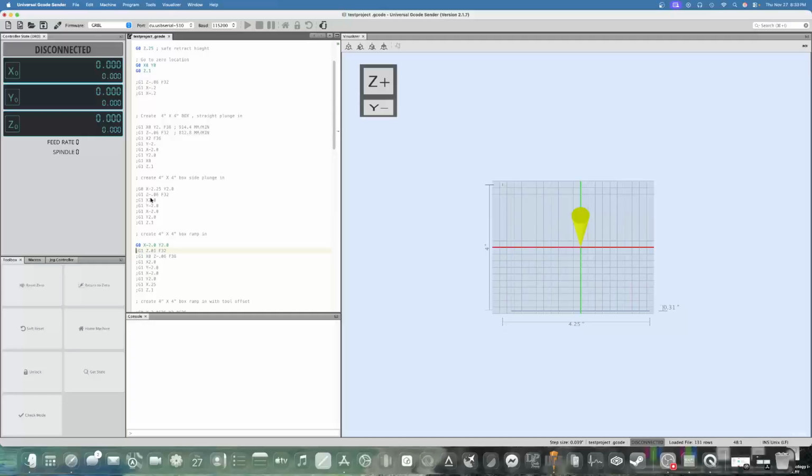So the next option is to ramp it in. And then when you're writing G-code, you notice like these first 2 lines. This is a G0, which is a rapid movement, and then a G1. Just like if you notice the feed rate off to the side, there's one feed rate of 32 where it's feeding the Z down.